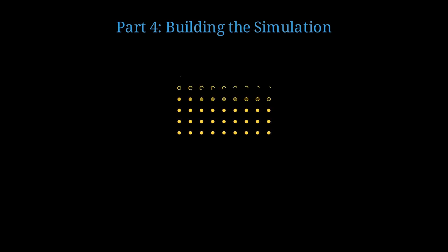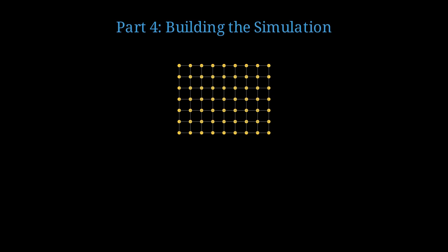How do we simulate this physics computationally? Let us discretize the problem. We discretize space into a finite element mesh. Each node tracks temperature and moisture. Grid spacing determines accuracy versus computational cost. Finite difference approximation of the heat equation: temperature at node i and time step n+1 depends on neighboring temperatures at time n.